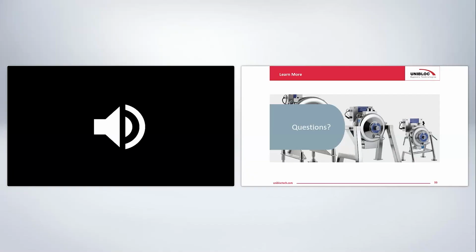I've also seen people in the chocolate industry who are using gear pumps for recirculating the chocolate through some of their mills. And they also find that the AODD saves them time on the cleaning. It's a lot easier to jacket an AODD pump, so they keep the temperature of their chocolates correct.